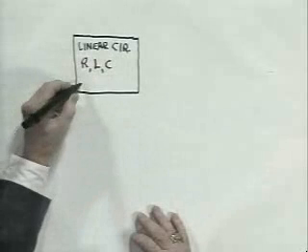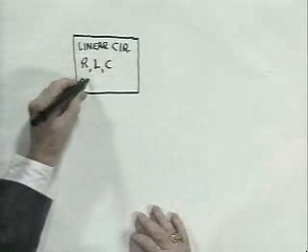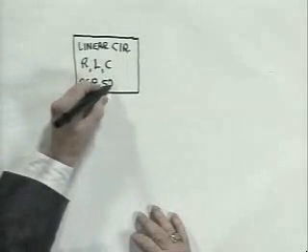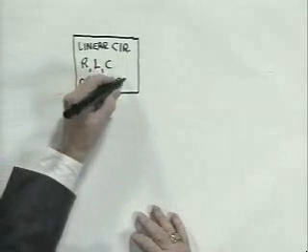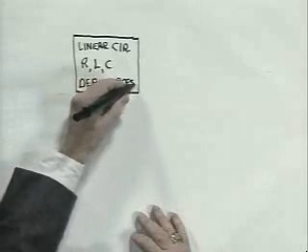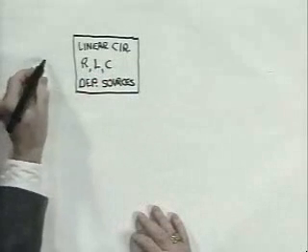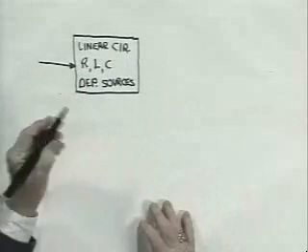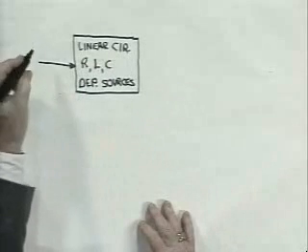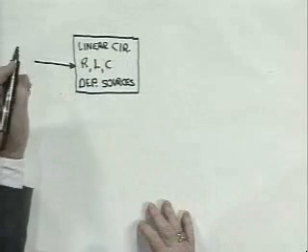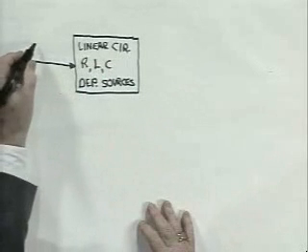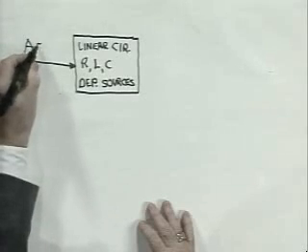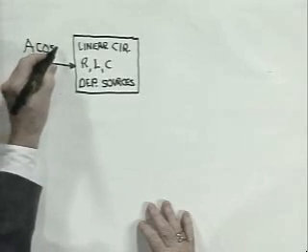And if it has any sources at all, they are dependent sources. Now, we drive this network at some point, a voltage source, a current source, with a signal or a function of the form some multiplier, I'll call it A, cosine omega t.